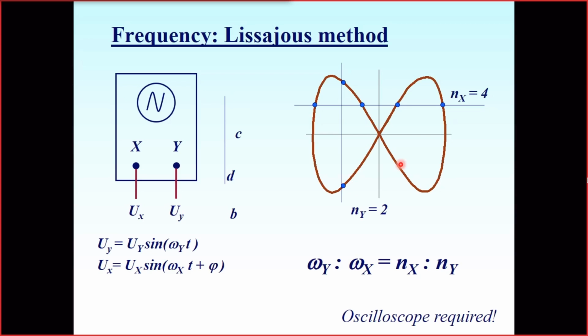You have to find a scope, you have to find a generator, and you have to be sure that your measured signal is an accurate and stable sinusoid. But for the etalon measurement, when we try to calibrate one generator using another generator, this method is very good, because the accuracy of this method, as I said, is really huge. It's defined only by the accuracy of the reference generator.